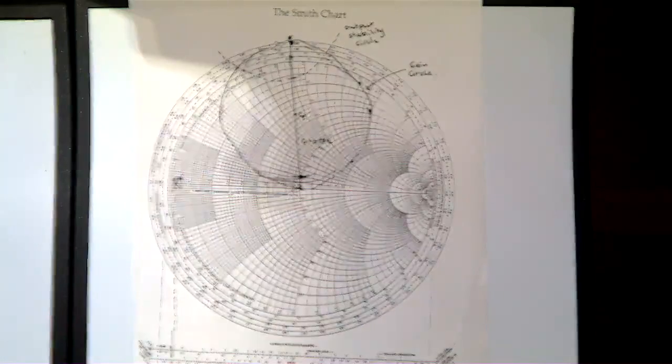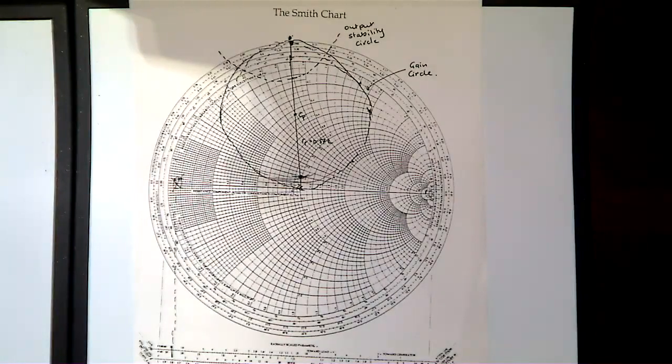Here I've just said you can do it, you get a value, but the value is not a great value, right? It gives you the maximum, it gives you the 10 dB gain, but the problem is that it's also giving you a terrible voltage standing wave ratio. In a real system, you don't want that. If you're designing a power amplifier, you don't want that, right?